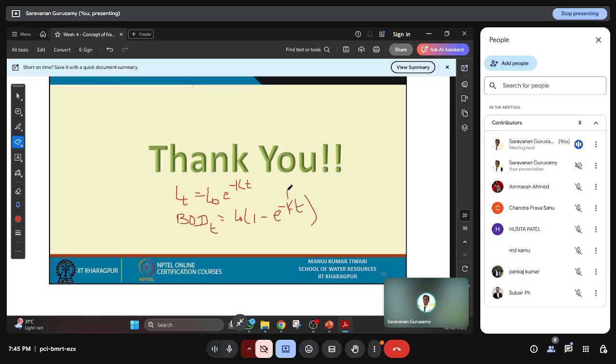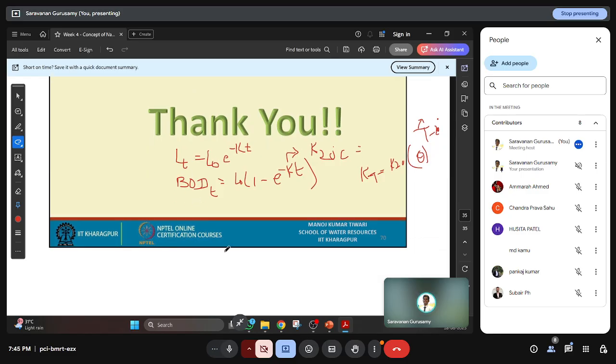K will be found at 20 degrees Celsius, and that will be given. If you want it at any temperature, K_T equal to K_20 into theta power (T minus 20) is the formula. Theta will be given, and you can substitute that temperature. That's the formula we have seen.